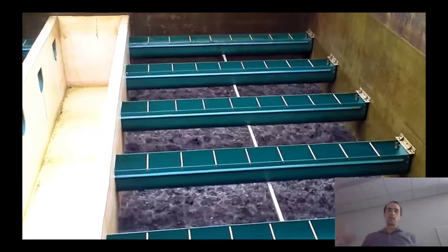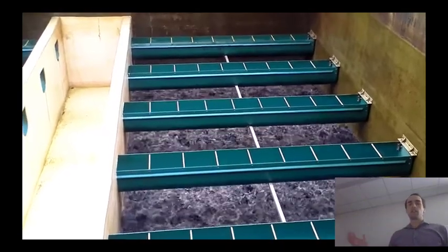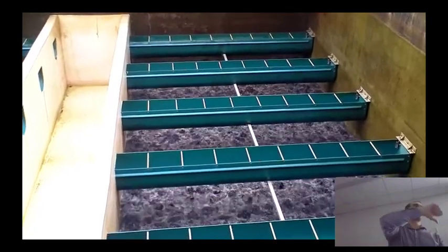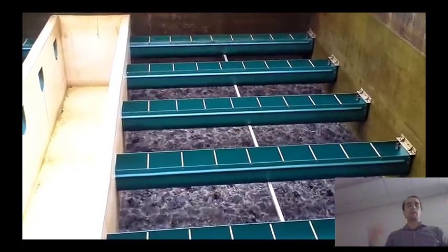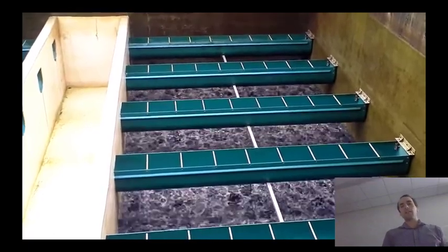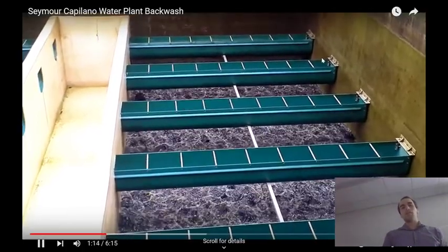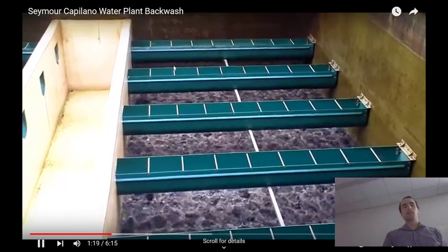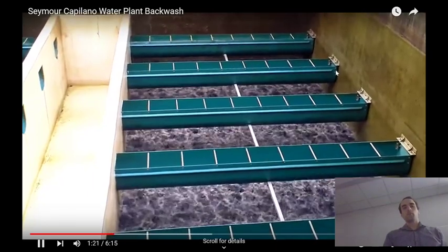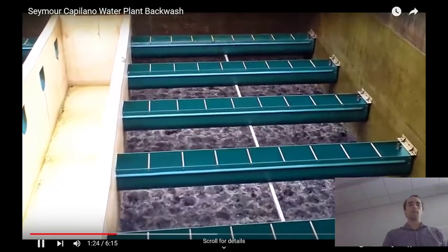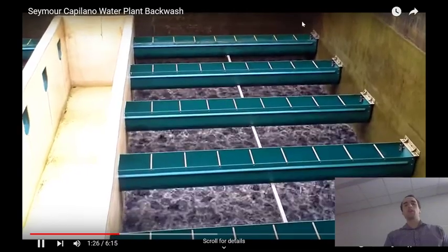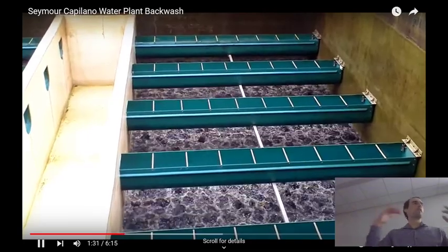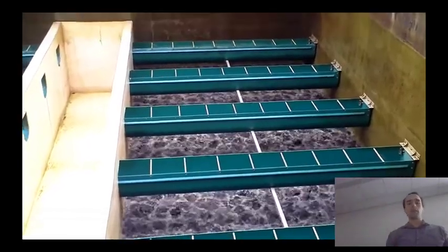As we'll see here today, in this moment, once I do the backwashing, the water is going to come, overflow into those troughs and then go backwards through this channel system. That's just the typical way they do that. And in a sense, there's an automatic stop point, the water can't stack up much higher than that. I guess maybe you could if you pumped it in, but you're probably not going to operate in a way where your water's higher than that level. So there's a physical limit to how high you would stack the water in the first place.